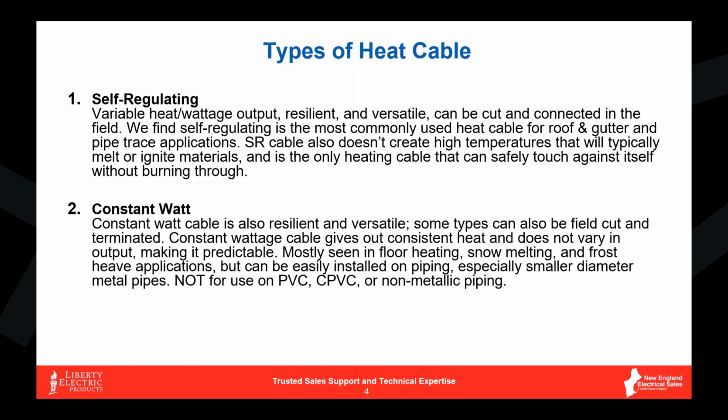Constant wattage cable is literally exactly what it says it is. This is a cable that can also be cut and terminated out in the field. Figuring out circuit sizes when we're dealing with constant wattage cable is a whole lot easier, because again, this is a very constant wattage output per foot. That makes it very predictable, versus the self-regulating nature that can roller coaster a bit with that particular cable. So we'll get into this a little bit more.